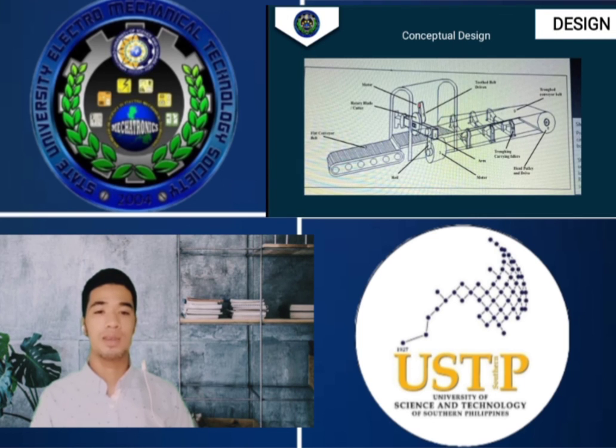Design. This is the sample design of the automated Abaca fiber cutting machine. For the input, we use a through conveyor belt system. It is also considered the feeder. We chose this conveyor system because of the bend design for better grip. We will bundle the fiber for fast production and better cutting. The head, pulley, and drive will make the conveyor rotate. The conveyor belt is supported by the troughing carrying idlers.